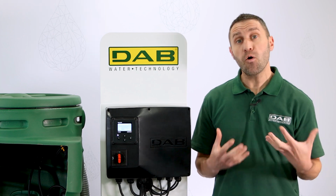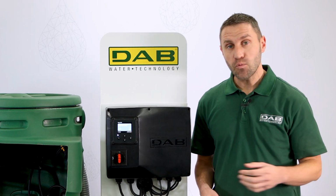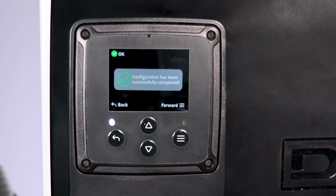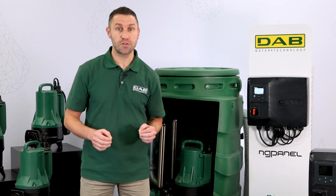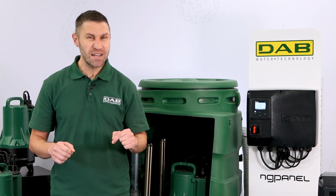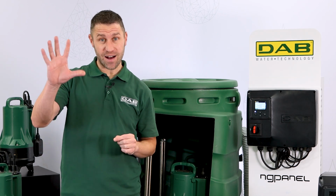We select how often the pumps exchange priority, and finally, we can choose to enable the flow rate estimation or not. And the configuration is completed. The advantages of the depth sensor is that I can choose the operating levels from the ngPanel without having to adjust the height of the float switches inside the tank. I only need to install one sensor that can do the job of 5 switches.